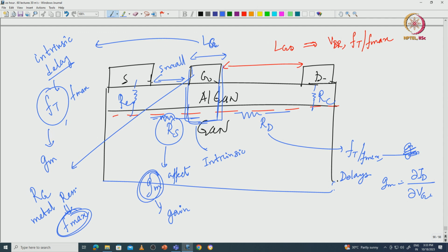Now as I told you, low noise amplifier has different criteria, switches have different criteria, but dominant market is power amplifier. So in power amplifier you are looking at 3 important things. One is the output power density, watt per millimeter. Of course eventually you are looking at watt, not watt per millimeter, but we will come to that little later. You are looking at gain and you are looking at power added efficiency, which is an efficiency. And of course you are looking at cost, you are looking at heat. Actually the way you manage heat will decide and dictate all of this. So how you manage the thermal part is very critical, otherwise you will not get the optimal performance.